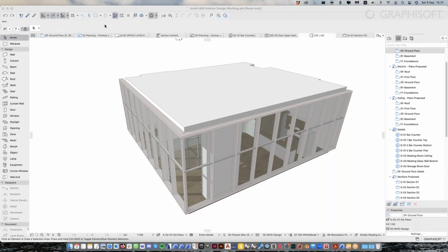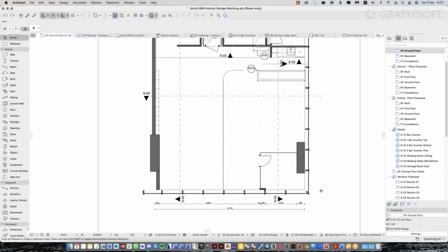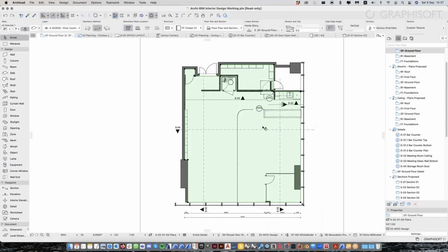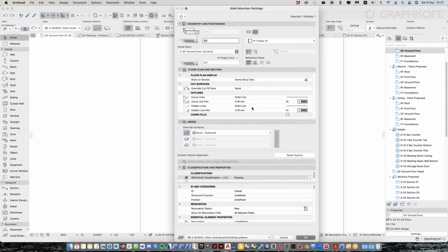And I think that was just a quick question about showing the hatches, right? You want to indicate the materiality of this, because like I show on the other, you want to maybe show horizontal lines for this and the tiles for that. So now this is, let me see, yeah, it doesn't have a cover fill, so that's why it's not really showing any hatches.